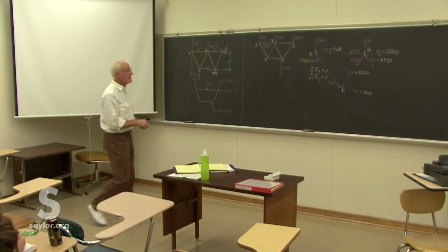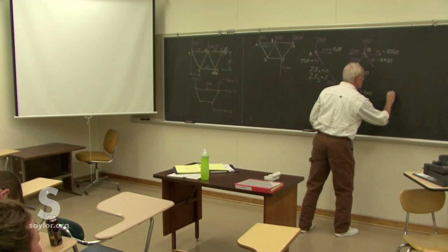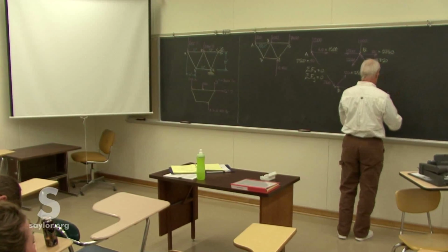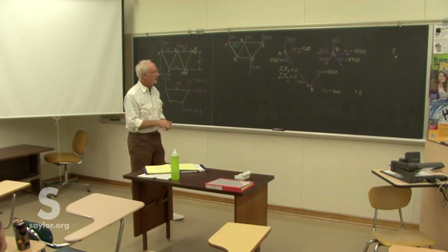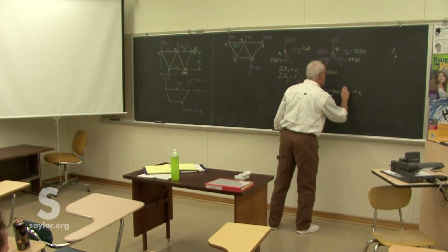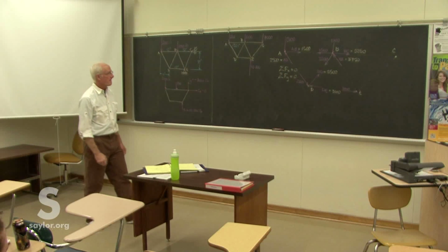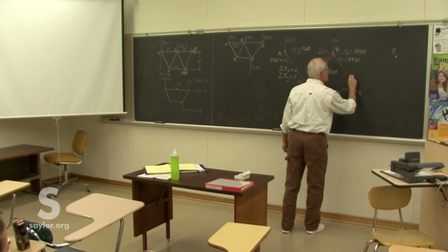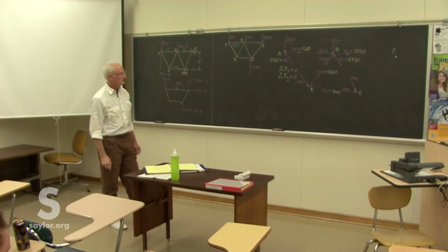All right, we keep going until we finish the problem. We've got two more joints to do, E and C. If you know any forces, you put them in. Let's see. We know that's got to be that way, and is 3 grand, because that was what was going on at the other end of it. We know that one's 3750, simply because that's what was going on at the other end of it.